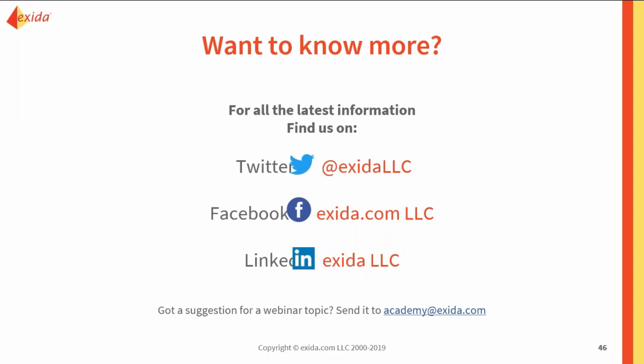The next question we have: does IEC 61508 or IEC 61511 mandate third-party certification for final element certification? I have seen end users accept manufacturer certification as is, and a lot of those numbers are very optimistic. Yes. So there are multiple questions in this. First of all, the standards, either IEC 61508 or 61511, do not say a third party has to be used. It says it's up to the end user and the device manufacturer to agree upon that. However, it does say you need to have realistic information.